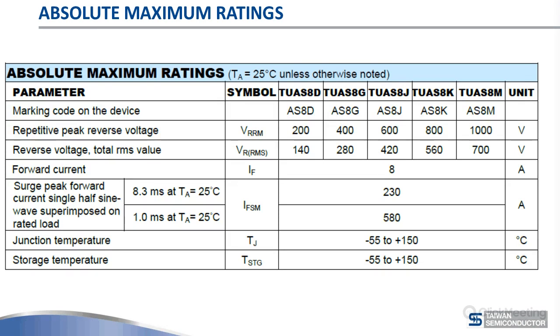Talking about junction temperature is a little bit like philosophy. It is a maximum rating and it is not a maximum rating. We'll talk a little bit more in detail about how you can look at the junction temperature in different ways. One thing I would like to point out about the surge current here is that it's usually given in a data sheet at 8.3 milliseconds or 10 milliseconds. A lot of designers will say, why?